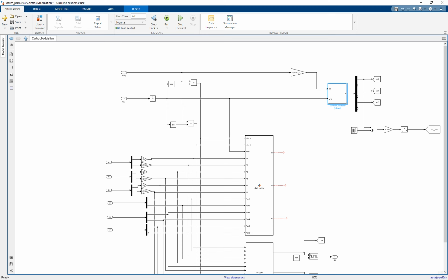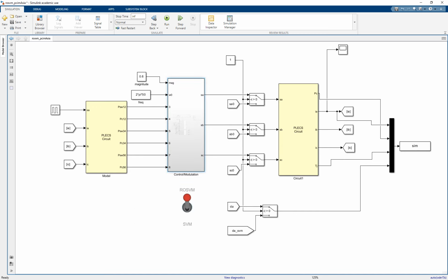Up there, I have this built-in MATLAB space vector modulation 2-level to compare the results with and to see how it works. So this is a simple mechanism to calculate the duty cycles. Maybe I could look under the mask and put this inside, but I put it outside after computing the pulse waveform.